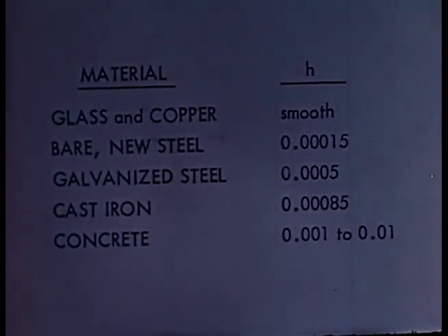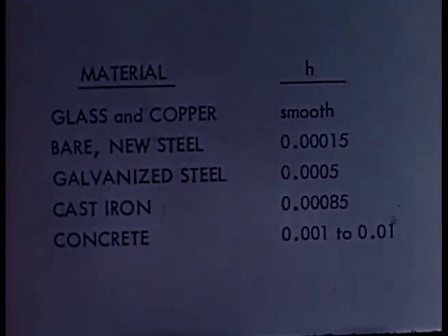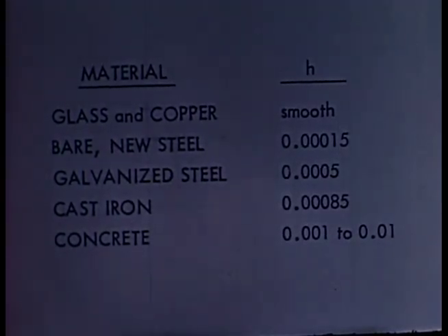Such a diagram is accompanied by a table of equivalent roughness height. Since height is only one of several characteristics of surface roughness, and the chart is based on the averages of many different surfaces, any given experiment, especially when uncommon surfaces occur, may differ considerably from the values given by the chart.